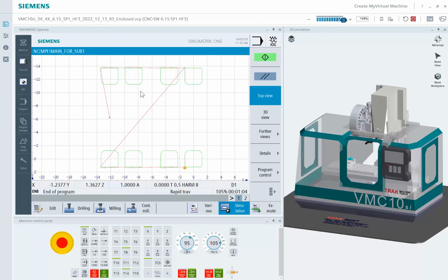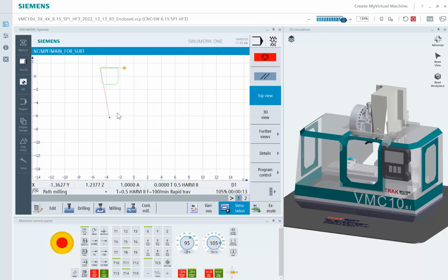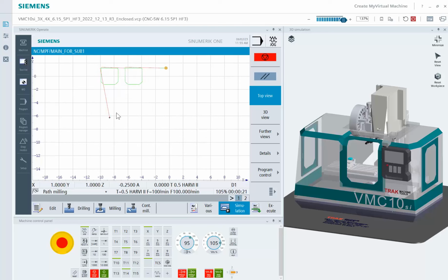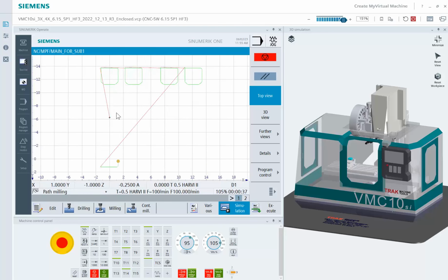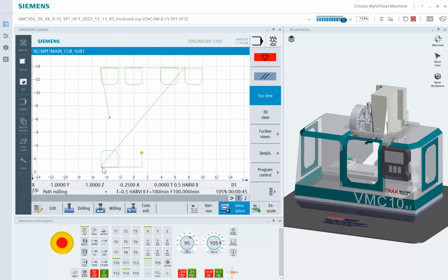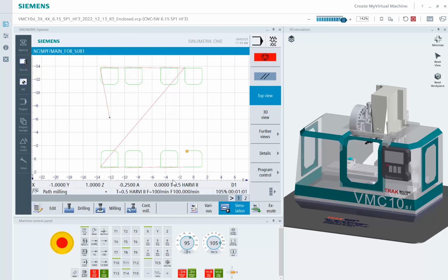Now, one of the downfalls when you start using mirror is the machining path or machining direction because everything's mirrored. So what is conventionally milling up top, right? If you look at the top, I'm going around clockwise around an outside profile. So I'm climb milling, excuse me. But now in the bottom, I'm conventional milling, right? Now I'm going counterclockwise. So that's not an optimal cutting condition. So this is one of the drawbacks when you work with mirror.